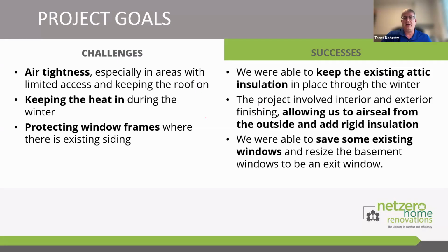The project involved interior and exterior work, and we focused on the air sealing primarily from the exterior, and we also added rigid insulation. And we resized a number of the windows and did relocate some as well. We increased one of the basement windows in size to make it an exit window.